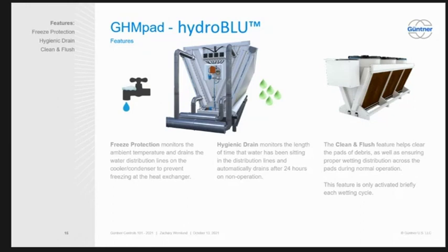Yeah, because we ran into that with a couple of them. We had a couple of humidity sensor failures and or people hitting them with things, and we ended up having to do the exact thing. We ended up having to override on the Belimo, but I didn't know if there was a way in the controls to actually force them on if there was a humidity sensor failure.